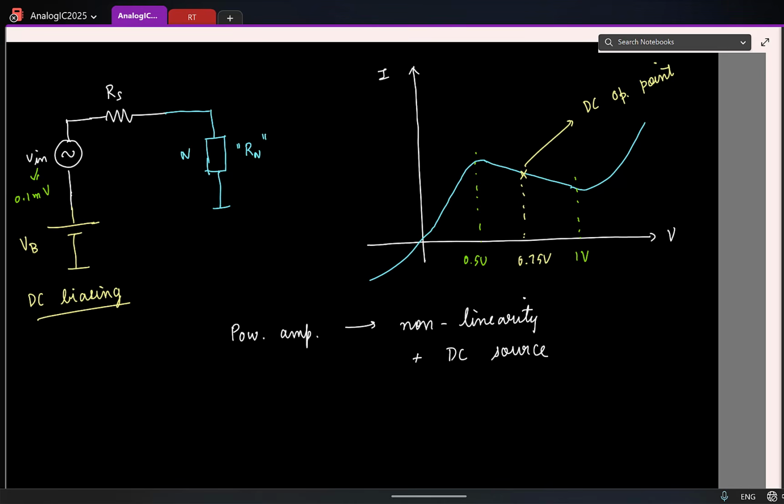So that's how an amplifier amplifies power. It borrows power from a DC source, converts that DC power to a signal power, and that's how you get more signal power. So, overall energy is still conserved. Which means if I just had a truly linear and time invariant network, remember, in an LTI system, if the input is at a sinusoidal frequency of f0, the output will also be at the same frequency. In other words, you cannot have any kind of frequency translations with truly linear and time invariant systems.